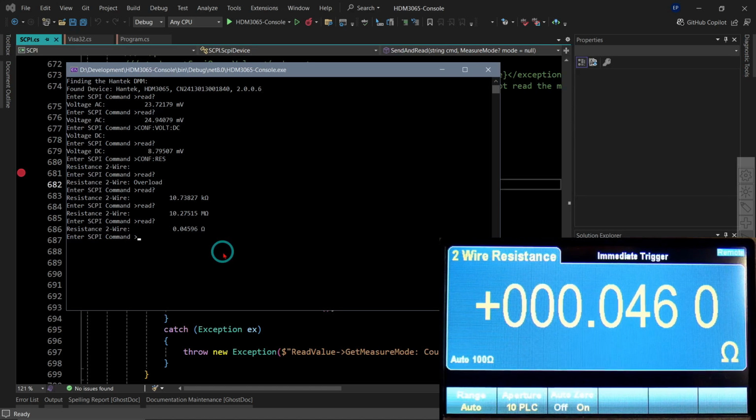In any case, that's working. So we should actually be able to use this multimeter right down to a milliohm meter, but I've got dedicated milliohm meters which I would prefer to use. They have extra features. You can zero them out and stuff like that.